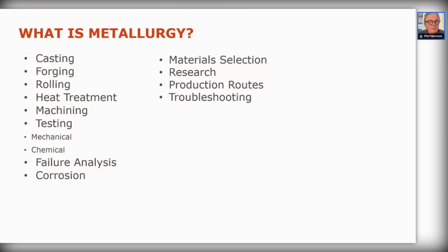And then when we've done that, believe it or not, metallurgists look at machining. Quite frequently, there are machining problems with materials. This can come down to various different things we do with them. For example, metals can be heat treated to make them easier to machine. An example is spheroidizing annealing of steels, where they are heated to a temperature, held for a long period of time, might be as long as 12 hours, and it creates little shapes in there which facilitate easier machining of the material.